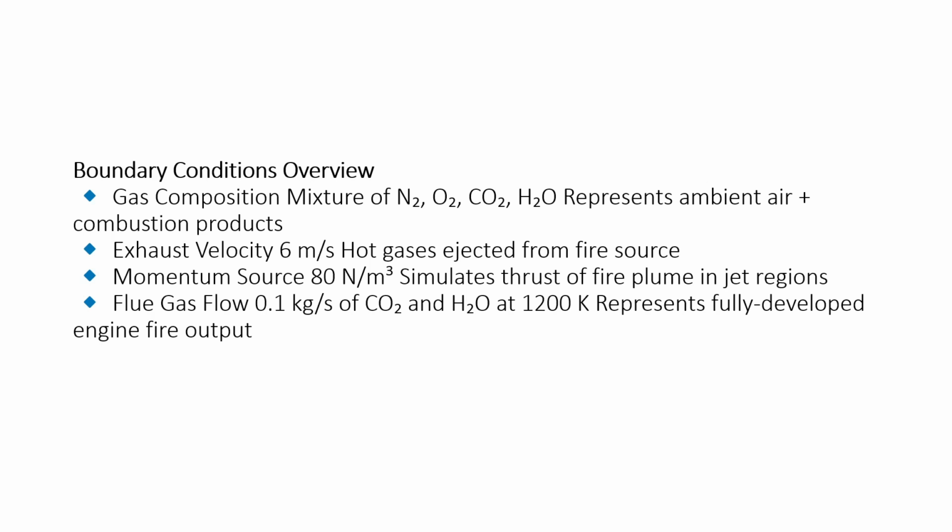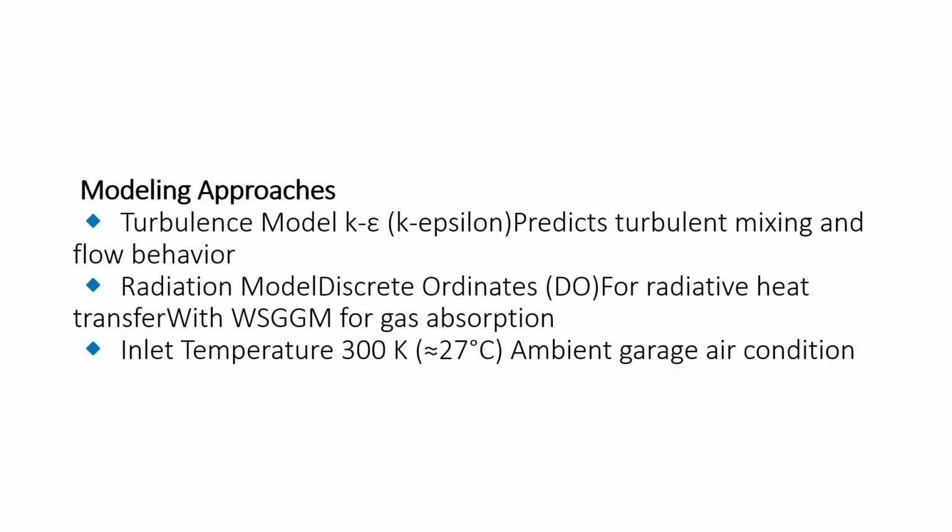Flue gas flow rate: 0.1 kilograms per second at 1,200 K. This is the mass flow rate of the hot gases being emitted from the engine fire. The temperature of 1200 Kelvin simulates a fully developed fire scenario. Turbulence model: k-epsilon. We're using the k-epsilon model, which is one of the most common turbulence models in CFD. It helps us accurately predict how air and smoke mix and flow turbulently in the garage.